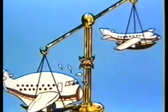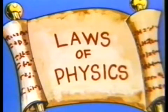Now imagine that same heavy coming in from a ferry flight and landing with no passengers, no baggage, and only 1 hour of reserve fuel. It doesn't take a lot of figuring to realize that the airplane in the second example could weigh 100 tons less than the max weight airplane, and that there will be a significant difference in VREF speeds between the two. Now, since the laws of physics apply equally to small airplanes, they too must have different approach speeds for different landing weights. And flying the appropriate approach speeds for these reduced landing weights is a necessity to avoid landing long.